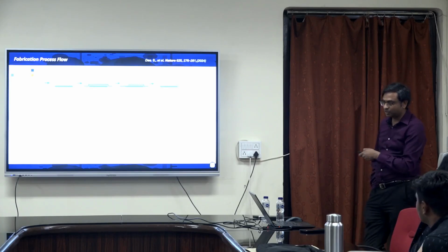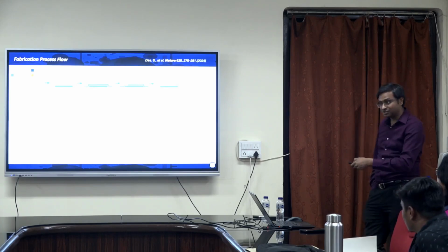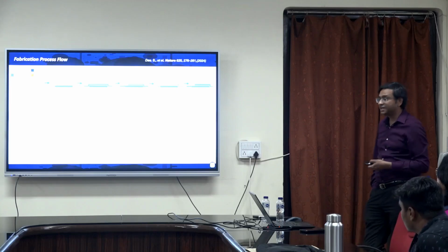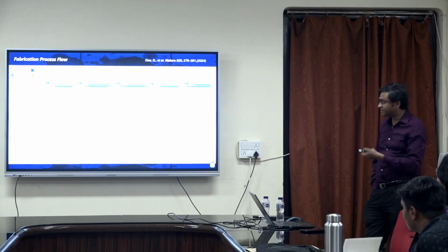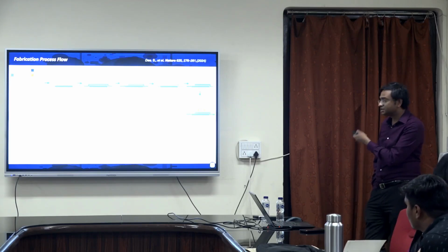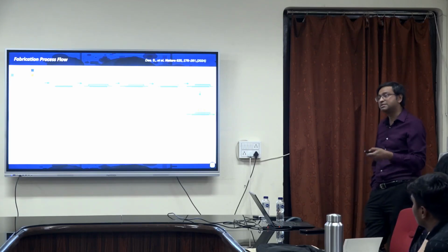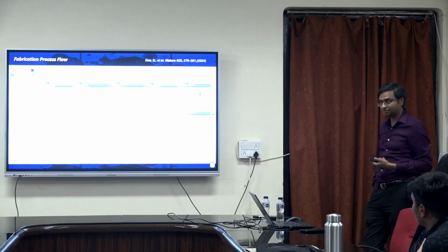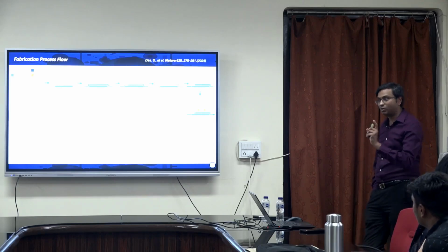Then we transfer the MoS2. Then we again pattern using E-beam, right? And then we etch the MoS2, right? Then now I have a channel, I have a dielectric, I have a metal electrode. Then I do another E-beam lithography and E-beam evaporation to put the source drain contacts, right? This is how we make tier 1.